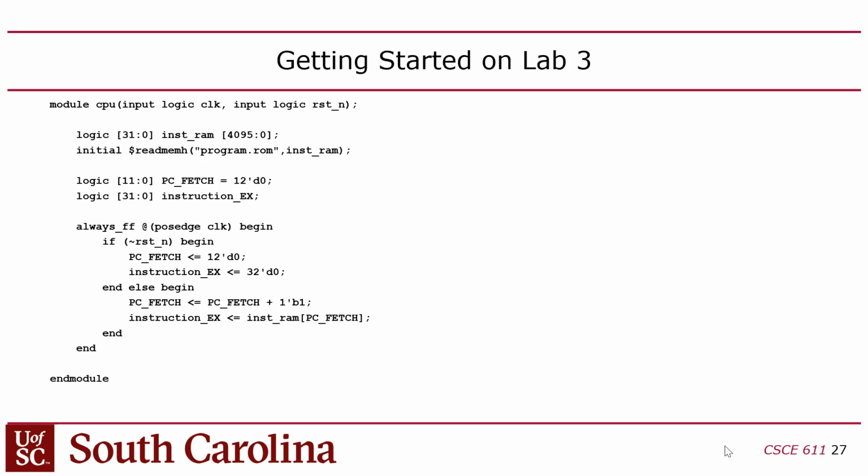Now, we don't have any way to change the flow of the instructions because we don't have branches and jumps yet. So you might say, well, wait a minute, what happens when it finishes running the program then? The program counter will roll back to 0 like an odometer, right? And it'll keep cycling through the program infinitely. So whatever program you put on here will automatically be put in an infinite loop because the program counter rolls back over to 0 and then it keeps repeating.